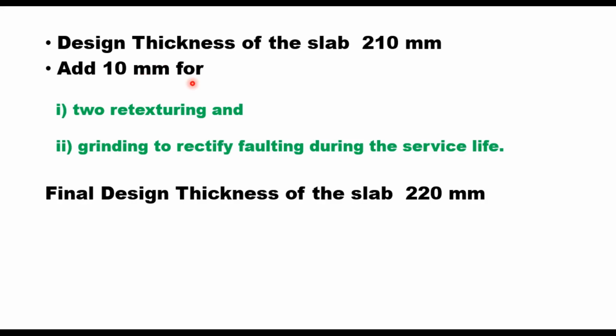Let us add 10 millimeter for retexturing and grinding to rectify faulting during the service life, and therefore the final design thickness of the slab will be 220 millimeter or 22 centimeter.